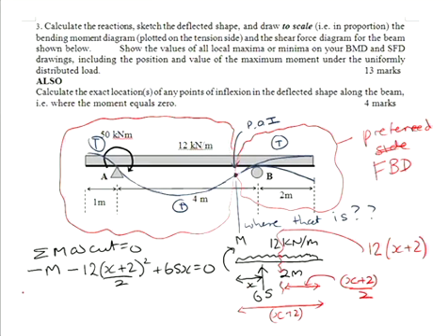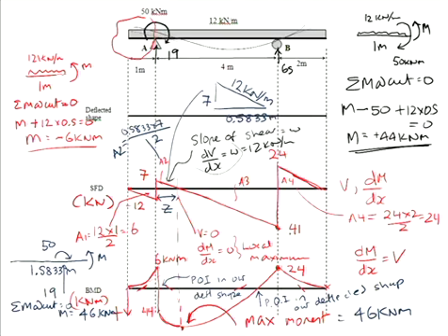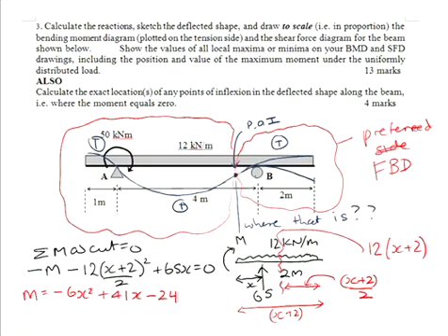And when I simplify it all down, I get that expression for my moment. So that is an expression for the bending moment, not everywhere, but from this point B through to the other point. Why didn't I show you on here? This expression is valid between x equal to 0 at B through for 4 metres, because I've got no singularity brackets in there.